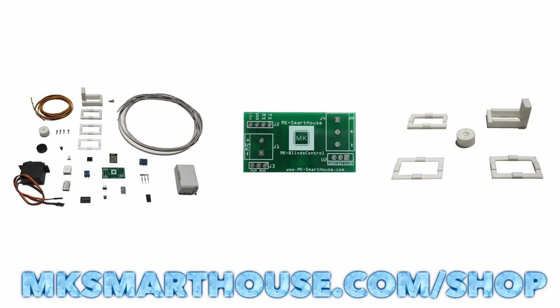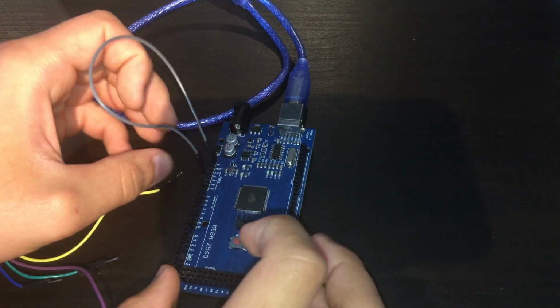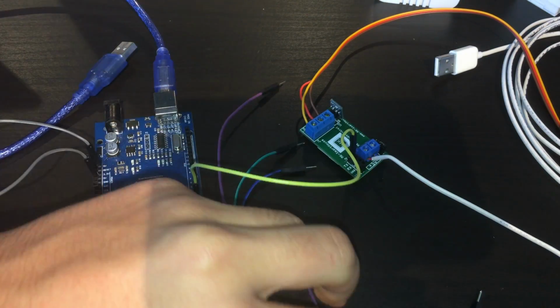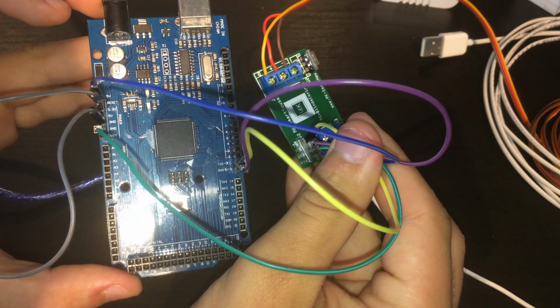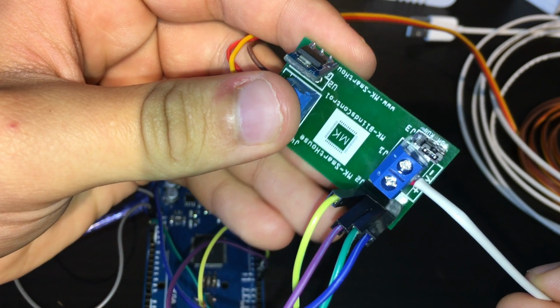The first thing we're going to do is grab the Arduino and put a jumper cable from RES to ground. Then grab the blinds control and connect all the pins to their corresponding spots. So TX to TX, RX to RX, ground to ground, and 5 volts to 5 volts. Before we continue, check to make sure the 2-pin jumper is above PGM or program.